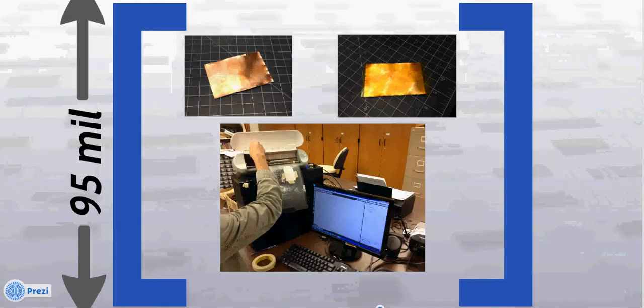We then cut the copper tape, place a piece of Kapton tape on top of the copper layer, and align it on the printer, placing the filter design on the copper tape. This is what it looks like when it comes out of the craft cutter.